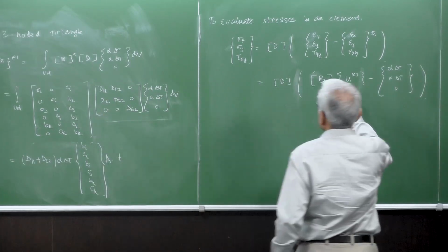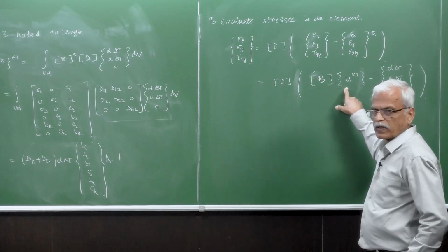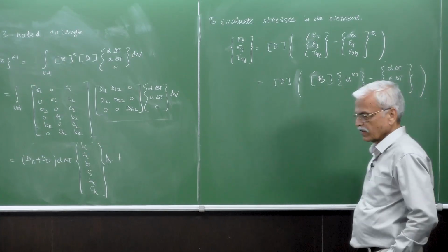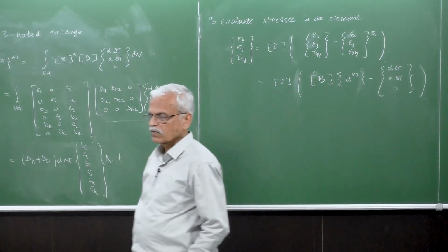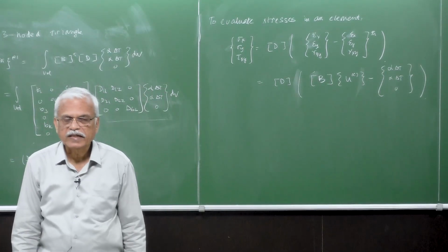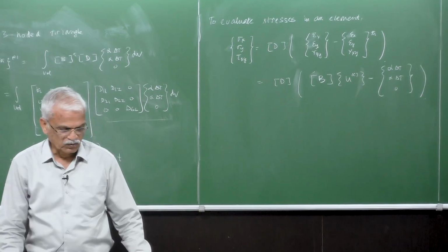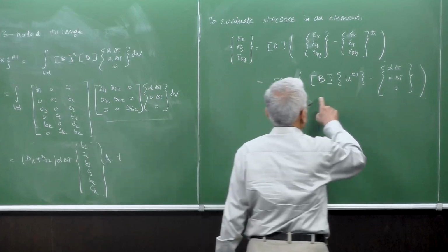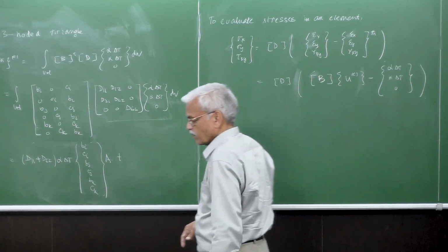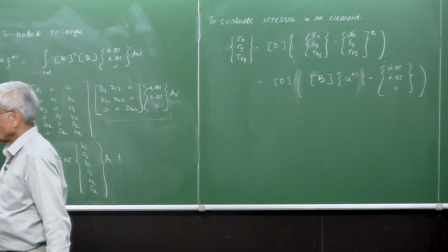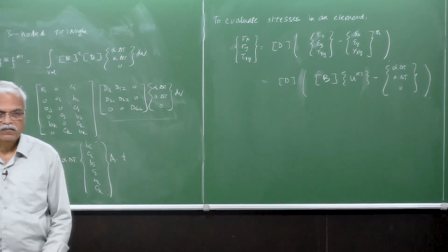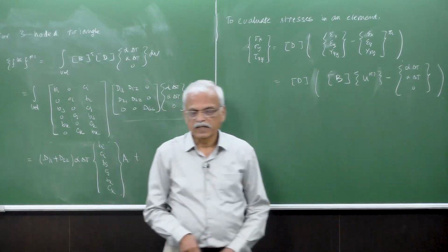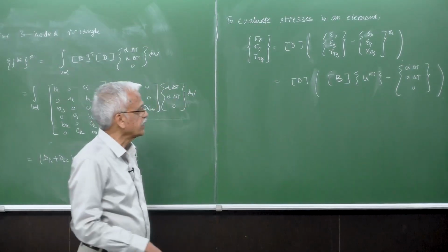That's nothing but the total strains minus the thermal component here. That will lead to the mechanical stress generated. Of course, this is a combined one. This is how we arrived at it when we put these things in the potential energy formulation, and then we had to bring back those equations to evaluate the stresses.